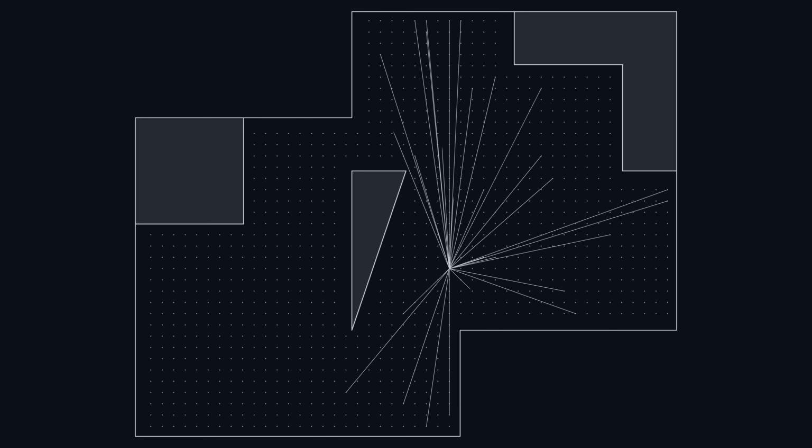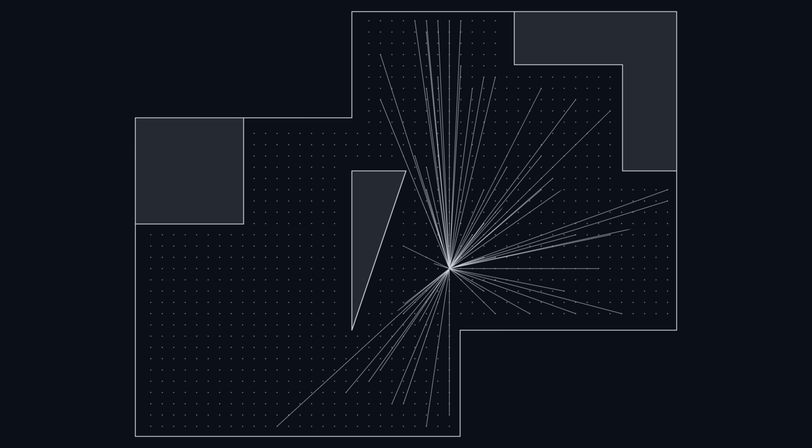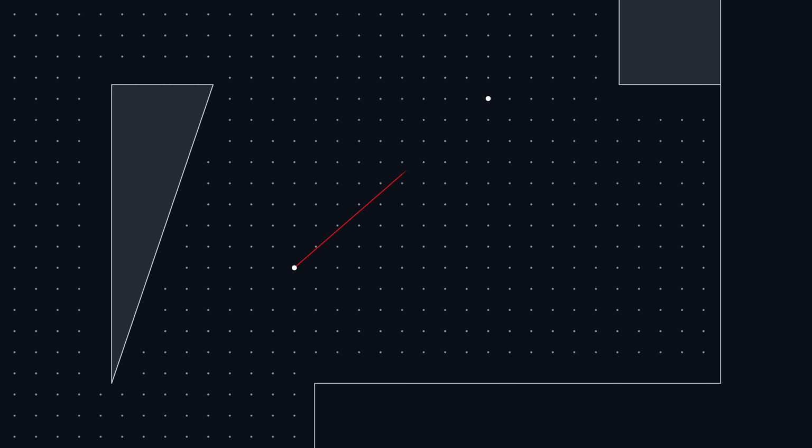You might think it is a good idea to allow the robot to travel to any of these vertices. But there's a catch. If we do that, the robot would have too many options at each vertex, which would make it really slow to decide. Let's focus just on two specific vertices. We can construct a path that gradually hops from vertex to vertex until the robot eventually reaches its destination. So we don't need to teach the robot how to travel to every possible vertex it can reach without hitting a wall. It is enough to show it how to move to neighboring vertices.